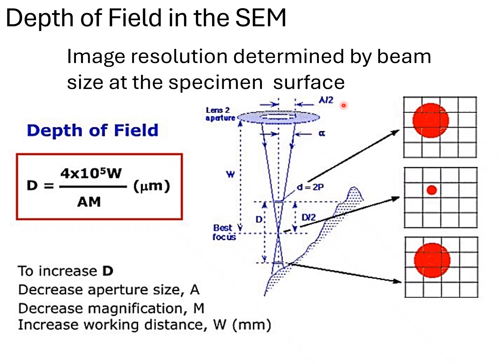Now, in an SEM, the image quality or the resolution of the image is dictated by the spot size, so where it intersects the surface. So when you have a small spot size that hits the surface at this point, we see a smaller sampling of the surface. And when you have a large spot size and you have a variation in the surface height, for instance, this variation will become less resolved.